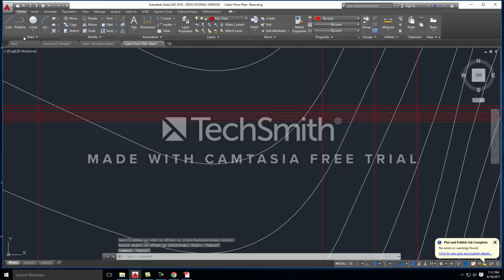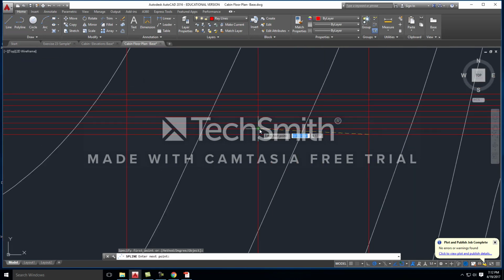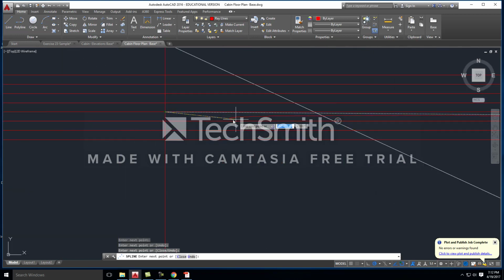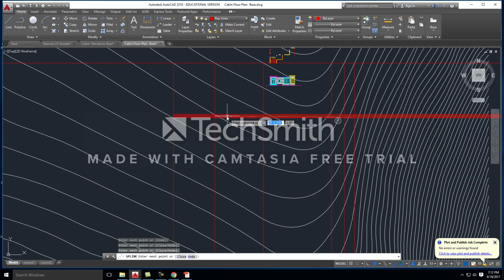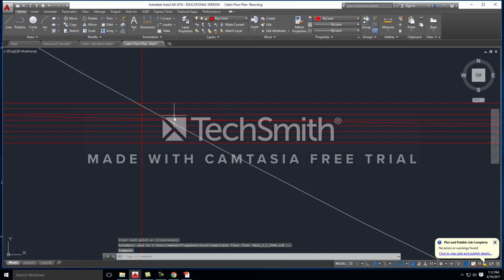Okay, so let's try that just one more time. So curve, spline curve, start here at the bottommost intersection, and we're gonna go 1, 2, 3. Let's see, 1, 2, 3, 4, 5. Okay, and then from there, I'm just gonna hit my space bar, all right? And I could see my curve there.